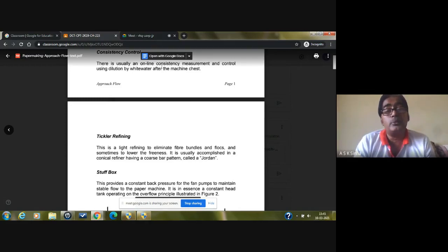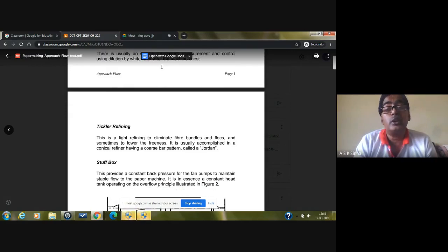So it's automatic basically with computerized controls. Normally in industry we have DCS control, distributed computer control, basically applied there, and with the help of the computer we can control the different parameters. So you don't have to do anything, it's already programmed, and we put in the value, control this much, and it will automatically control the solid percentage or consistency.